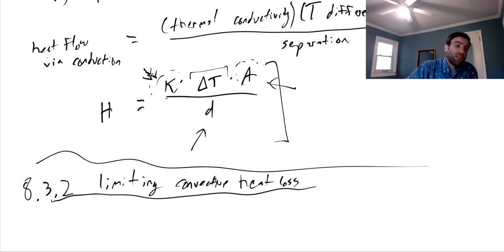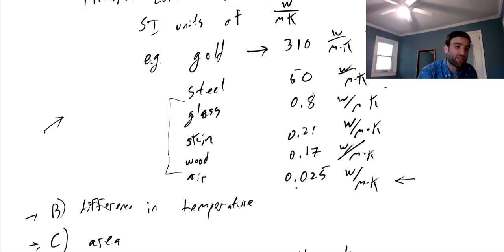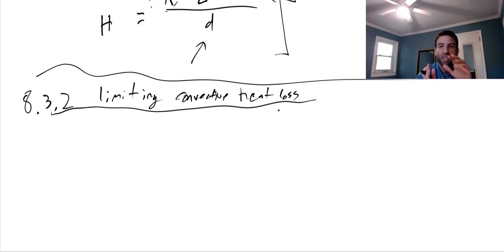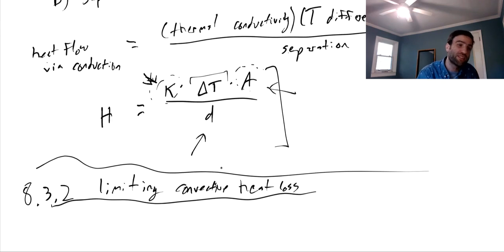Okay. Now, air itself is a very poor conductor of heat, which we know from this extremely low value of thermal conductivity relative to all of these other substances. And so actually, if you were staying perfectly still, you would only heat up a pretty thin layer of air next to you. Because air doesn't conduct heat very well, the body doesn't really heat up air far away. It really heats up the air molecules very close to your skin, right? So if you could get that air to stay still, then you really wouldn't lose nearly as much heat to conduction, right? Because the temperature of the air that's quite close to your body would be almost the same as the temperature of your body, right? And so this delta T would get pretty small, and you wouldn't lose very much heat to conduction.